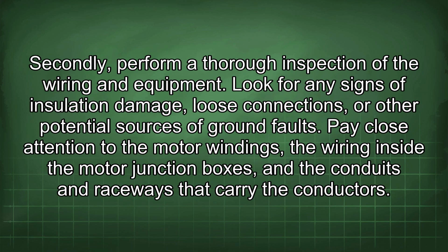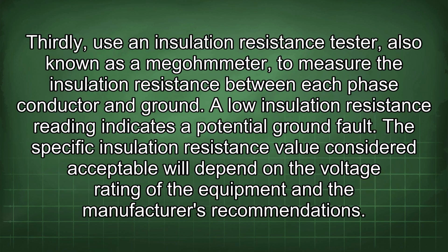Secondly, perform a thorough inspection of the wiring and equipment. Look for any signs of insulation damage, loose connections, or other potential sources of ground faults. Pay close attention to the motor windings, the wiring inside the motor junction boxes, and the conduits and raceways that carry the conductors.